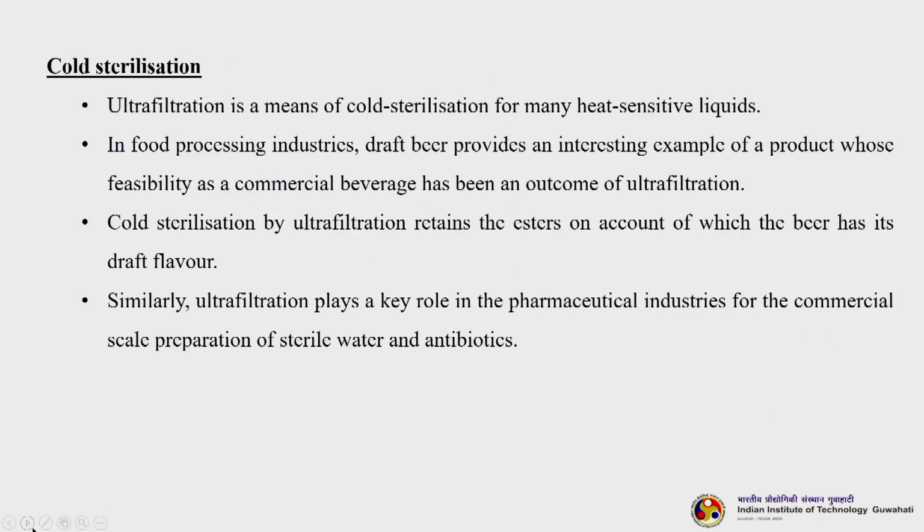The next is cold sterilization. Ultrafiltration is a means of cold sterilization for many heat sensitive liquids. In food processing industries, draft beer provides an interesting example of a product whose feasibility as a commercial beverage has been an outcome of ultrafiltration technology. Cold sterilization by ultrafiltration retains the esters on account of which the beer has its draft flavor. Similarly, ultrafiltration plays a key role in pharmaceutical industries for the commercial scale preparation of sterile water and antibiotics.